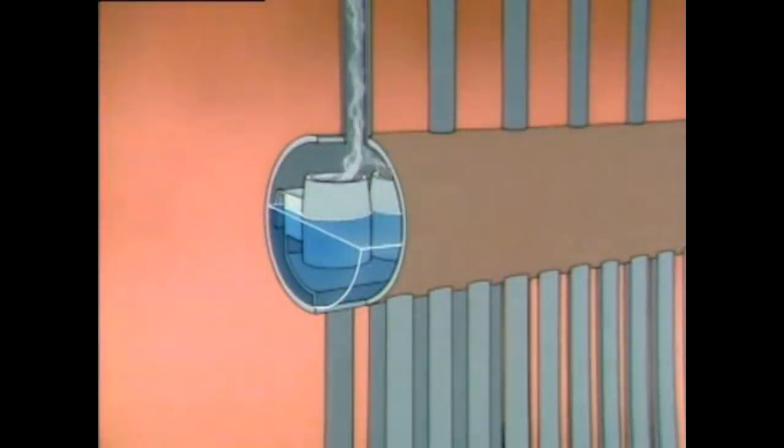The steam produced by a boiler generally contains some moisture. Some plant processes require relatively dry steam, so the moisture could be a problem. To prevent equipment damage from moisture, some boilers are equipped with moisture separators, devices that remove moisture from steam before it's sent to the plant. One type of moisture separator is a centrifugal separator, or cyclone separator, located in the steam drum.